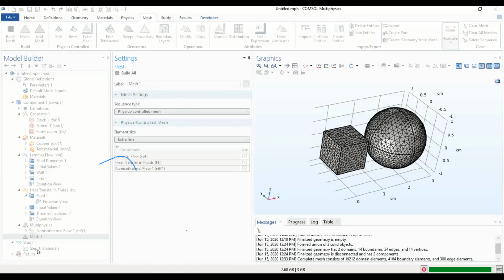You can also have reports as documents, a Word report, which we can take a look at next week, for post-processing our model. You can also export your results as a GIF or an AVI movie if you have multiple frames in your result. There are lots of ways you can slice into your geometry and see what's inside in the result. Post-processing using COMSOL shouldn't require you to use any other software to extract data, plot data, or present data out of your model.